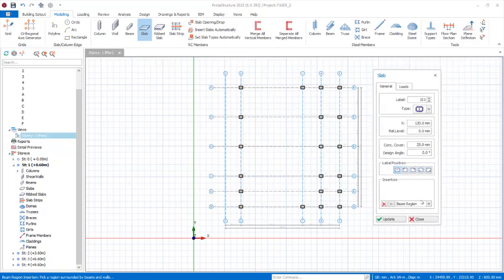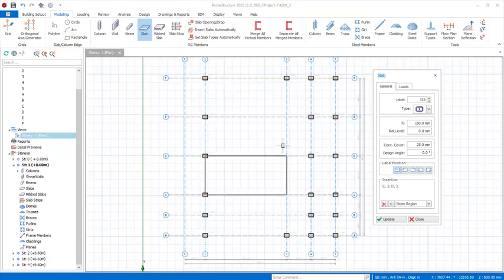Here is the slab dialog. In this dialog provisions, we'll be having a solid slab thickness of 150 millimeters, just like this. The slab we are going to be using at this level is going to be a mass concrete slab, and it's not a reinforced concrete slab.